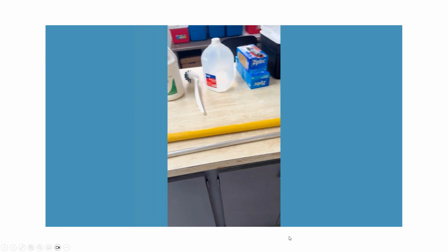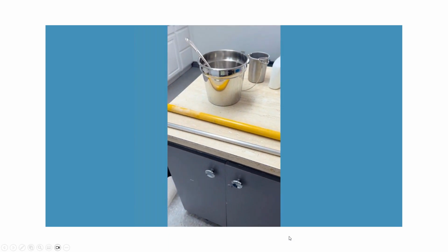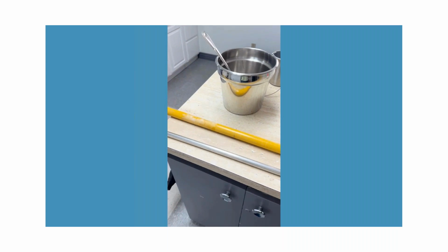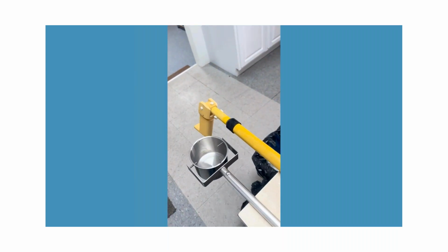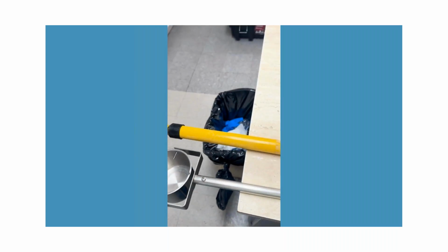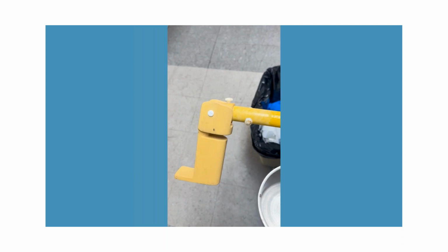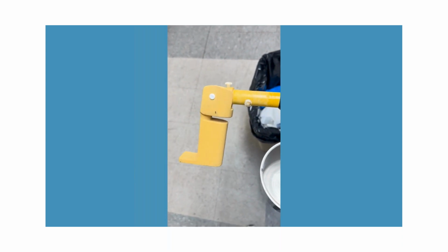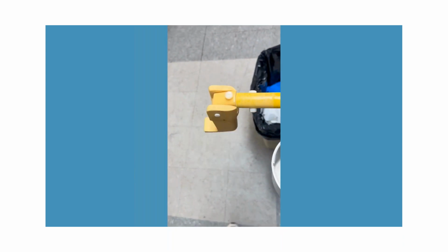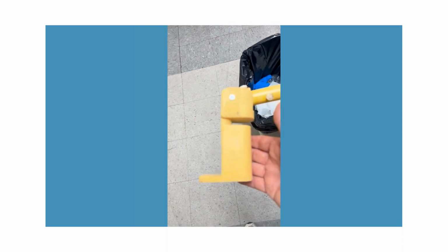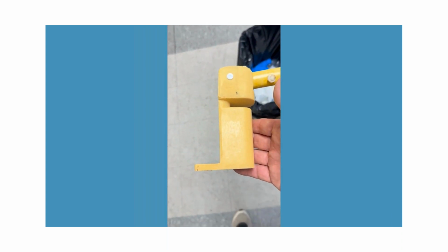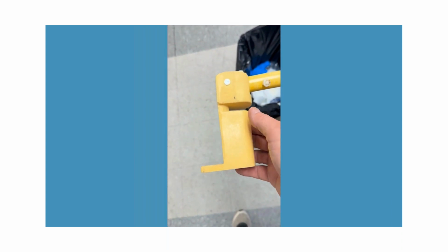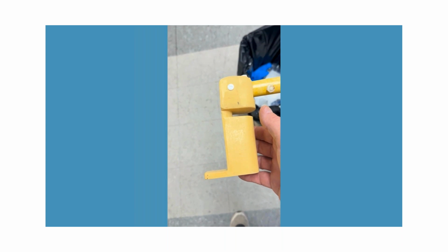Treatment plant effluent. Prior to sampling, evaluate the best equipment needed to gather a representative sample. For today's sampling, I'm going to be using an ASCO swing arm sampler that I've modified. I've taken all the metal components off and put HDPE components on. With a swing arm sampler like this, I can actually zip tie the sample bottle directly to the swing arm sampler and get a direct grab into the sample bottle, which is the preferred method.